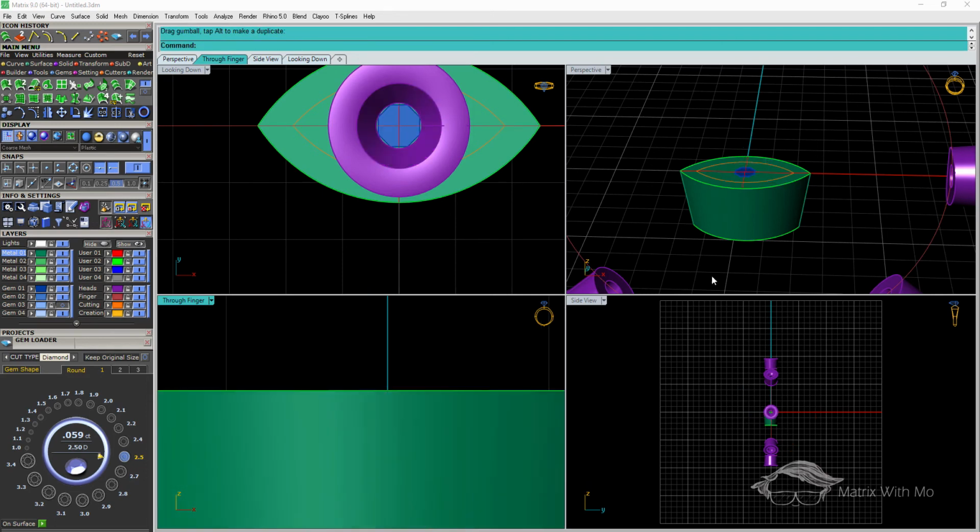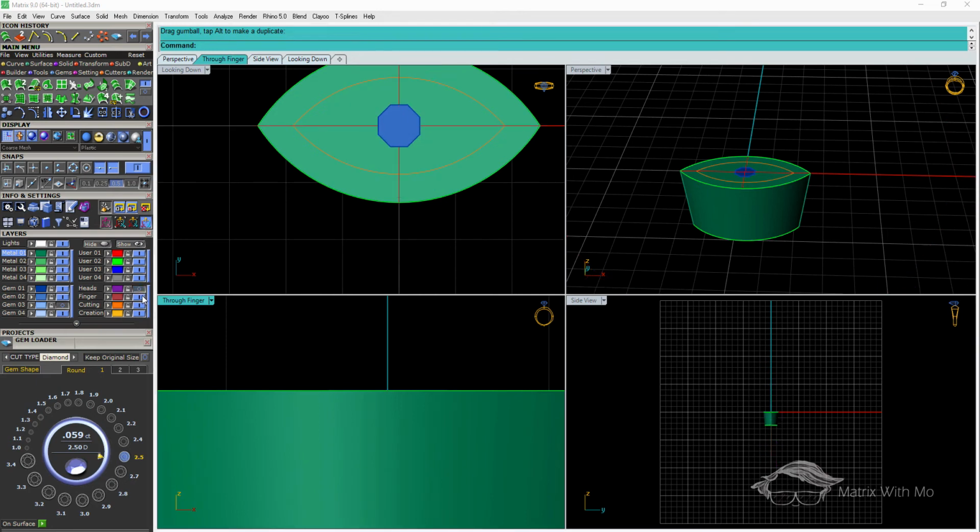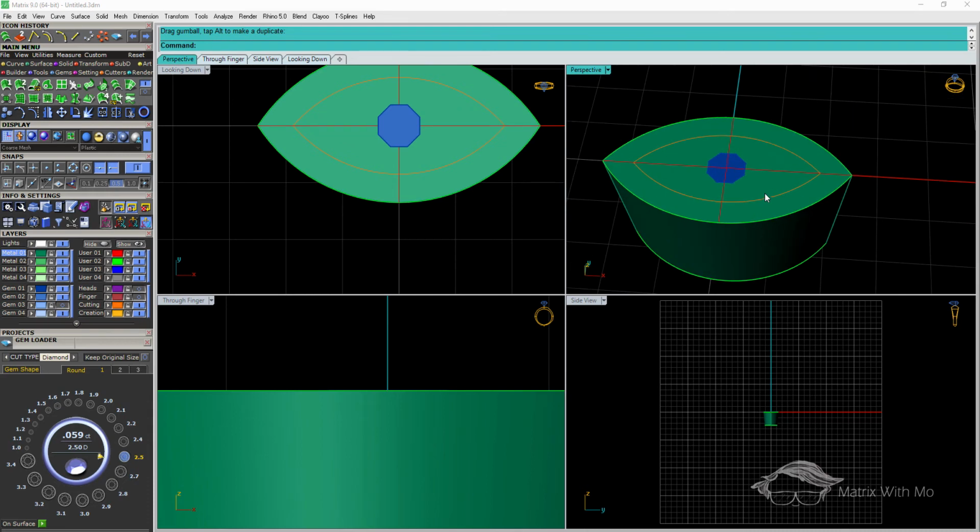That looks good. And now I can use, we had these bezels. Now I can use these orange lines, or offsets, 0.5 millimeter offset there to split the top surface and drop that piece down. So I'll click on the marquee shape, go over here to split, use these 2 curves to split it.